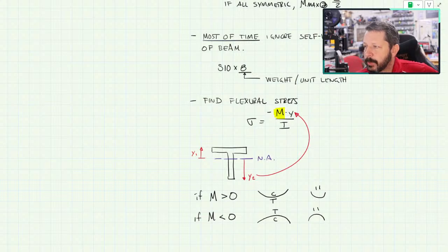Oh, I can confirm that there is one problem on exam 2 where you are specifically told to consider the self-weight of the beam. So that means look at that second number, and that is the weight. You just have to know what the units are. So if the units are set up as kips and feet and stuff like that, then that is pounds per foot.